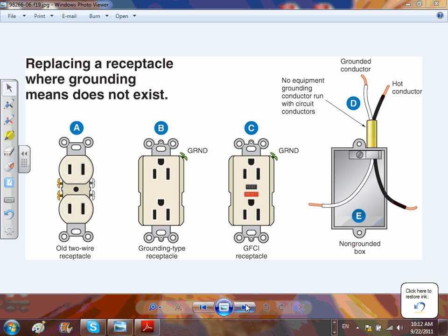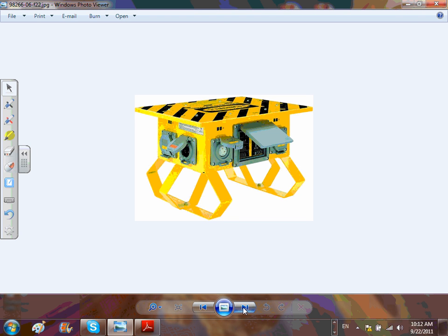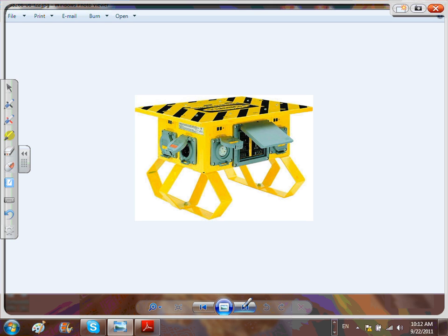Okay, moving on. If you're in construction and you don't have GFCI protection in the panel, the temporary service, that's what you should have: this power strip that gives you 15 amp. We'll talk about this as we go to the industrial guys. 15 amp, 20 amp, 30 amp, 120 and 240 receptacles have to be GFCI protected on a construction site.